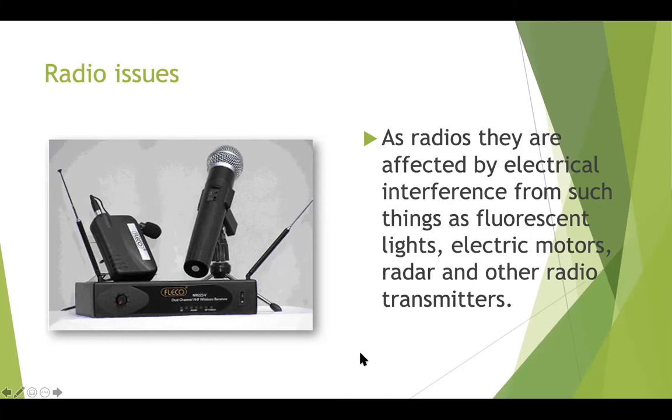It helps you troubleshoot. You start thinking, well, my radio worked fine in the building. It's not working fine now. Is it the battery? No, it's not the battery. Is it the microphone cable? You wiggle the cable to make sure it's not crackling. It's not that. Well, where am I? Oh, I'm in a generator room. We're at a bus station, trolley bus area. All those things are going to give off RF, and that'll help you troubleshoot those faults, right?